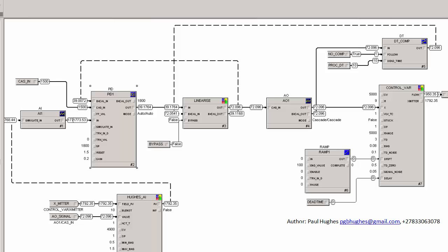This particular way of addressing flow and turndown problems I've used successfully in multiple places on multiple final control systems, and it always works. Specifically during startup, it assists the operators. What I often do is bring in this false or true flag, and you show it to the panel operator to allow them to be aware of the fact that the reading that they're seeing that's being used by the PID block is not actually the field reading. You can show them the raw field reading, but it's an estimated reading.